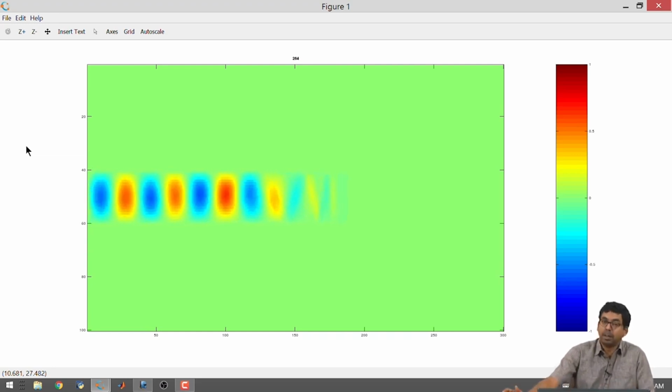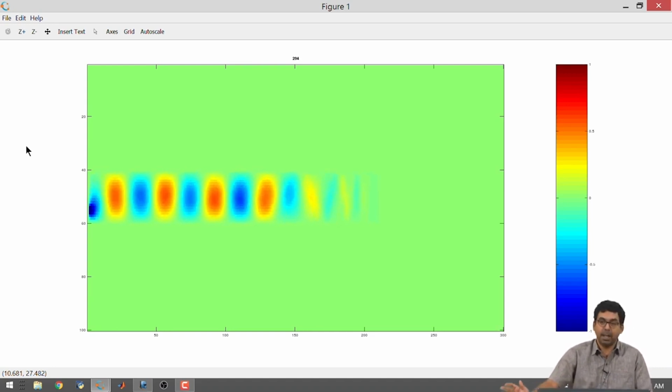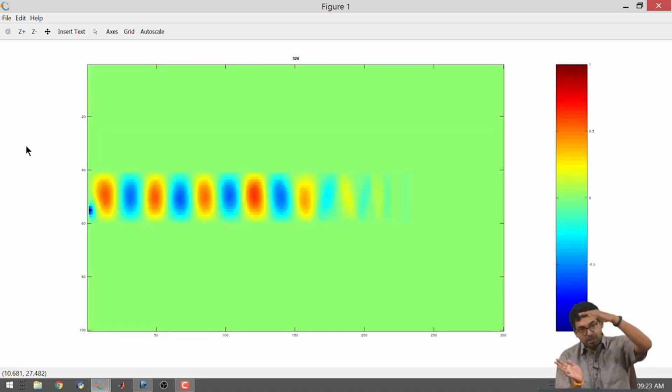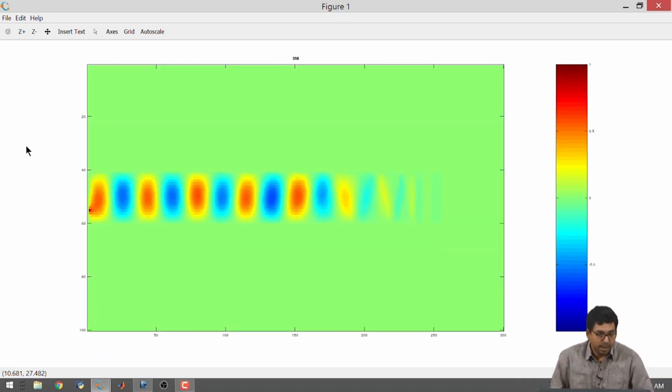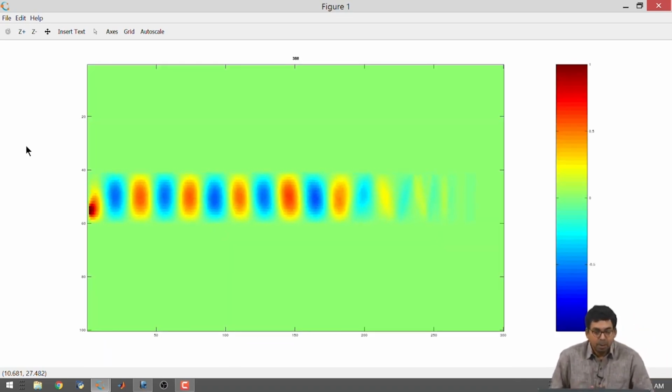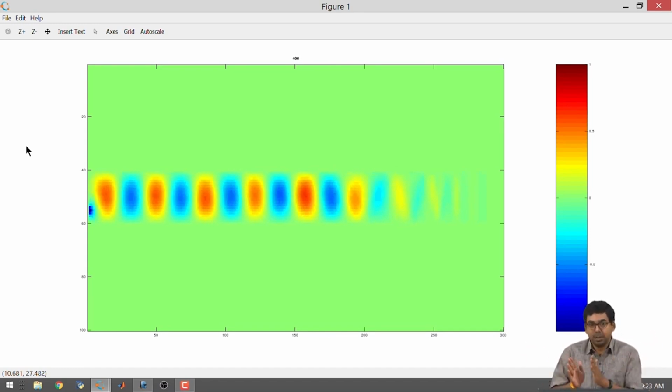Okay, now I notice something weird has happened. Previously, when I had the plates to be wider, when I kept a source largely asymmetric, I started to notice a different pattern, all right. Now, I made the plates go a little closer to each other and I kept the source reasonably asymmetric, I would say, but still I noticed that the pattern is similar, right. This should tell us something about the way we are making a choice of M in the case of these waveguides, all right.